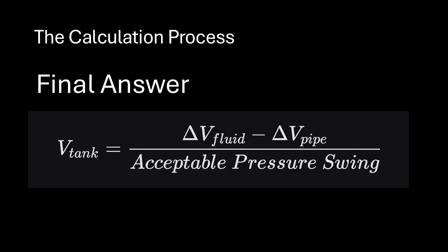If you don't account for the expansion of the pipe, you are only solving half the equation. Our model uses this full volumetric balance to ensure that your expansion tank is sized for the real-world behavior of HDPE, not the theoretical rigidity of steel. It's not just about fitting a tank, it's about understanding the synergy between your fluid and your field.